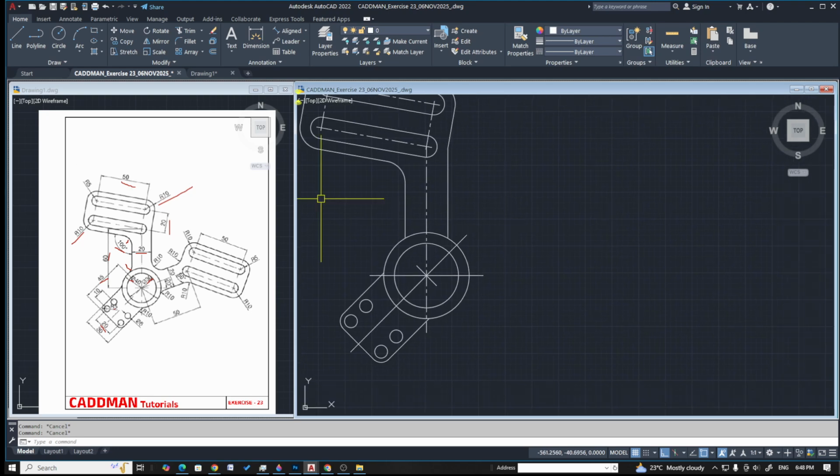And moving to the next portion of the drawing here, let's try to create this line first, which is 20 degrees with the horizontal. So what I try to do is I'll try to select the same line, go rotate, say copy. From here I'll try to rotate it in anti-clockwise direction by giving -20 value. Sorry. Rotate from this intersection point here, say copy.